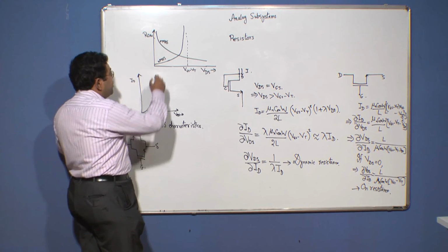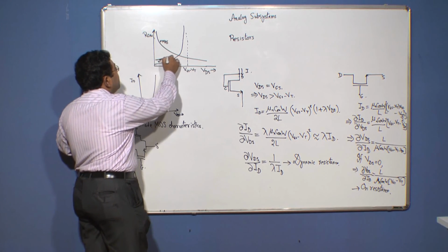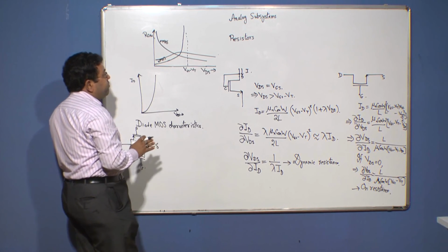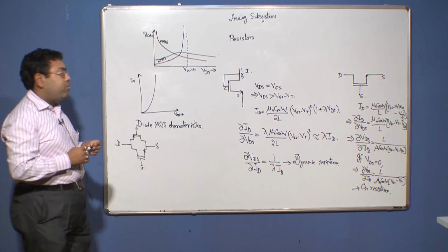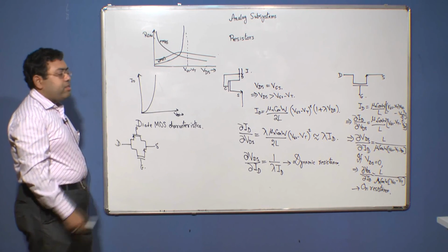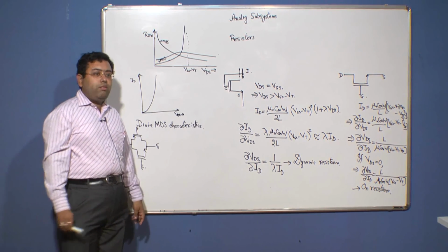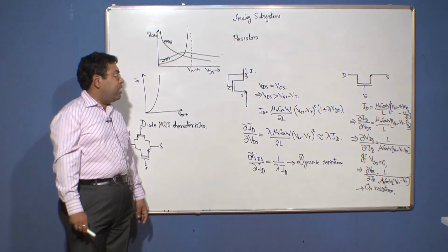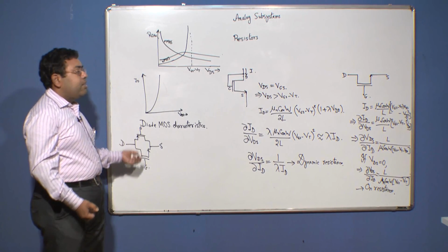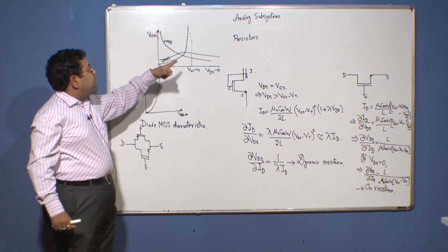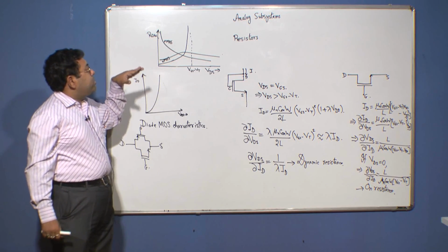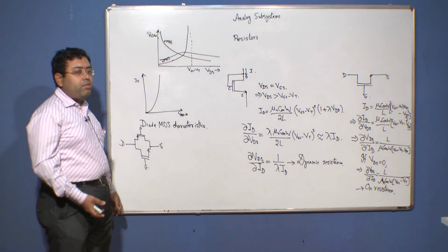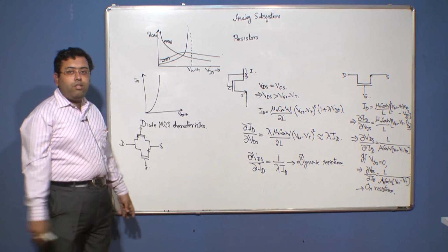And therefore with this parallel combination you basically have a resistance characteristics like this, which is almost constant over a very large dynamic range of voltage, and therefore CMOS pass transistors are typically used in most circuits instead of only NMOS or PMOS resistors. CMOS pass transistors, we can use as resistors because you can see that the resistance remains almost constant over a wide range of the terminal voltage, which closely resembles the ohmic behavior of a resistor.